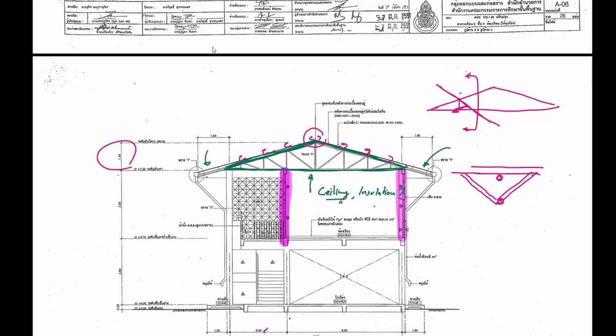But this building is not very high, like 7 meters. Generally, we don't bother with the wind load, except in some areas where you may encounter a problem in real life. Here, it's going to be an uplift. The wind comes in strong and blows up this portion of the roof. But for the time being, let's neglect this cantilever portion of the roof.